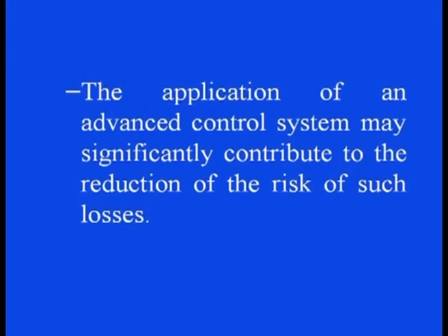Number 5, the ECM deterioration by sparking may cause irreparable damage to the intricate and often costly workpiece or tools, or completely shut down the machine prematurely. This risk rises at high machining speeds, which are normally associated with narrow inter-electrode gaps. The application of an advanced control system thus may significantly contribute to the reduction of risk of such losses.